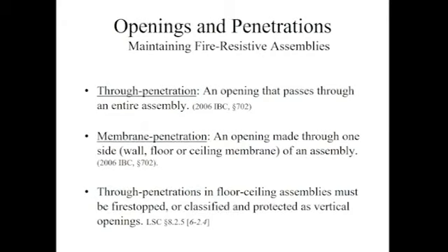But it has to be either treated as a vertical opening according to the sections of the code, IBC or NFPA 101, treated accordingly. Or if it's smaller, like a pipe or a duct or something other penetrating item, not an open hole, then you have to use fire stopping that is tested for a horizontal application, or rather the member going vertically through a horizontal assembly. And then all of these penetrations and fire stopping have to be installed, i.e. the products used for fire stopping have to be installed per a tested assembly.